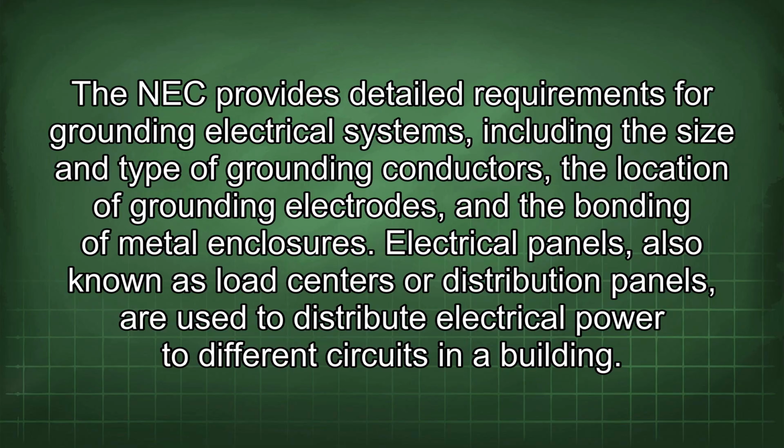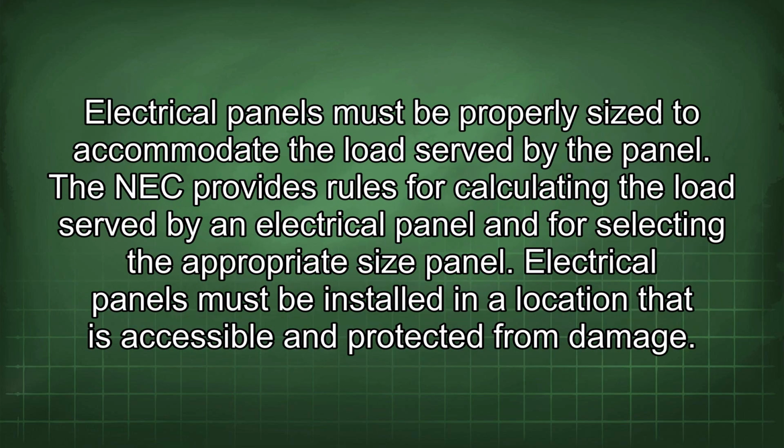Electrical panels, also known as load centers or distribution panels, are used to distribute electrical power to different circuits in a building. Electrical panels must be properly sized to accommodate the load served by the panel. The NEC provides rules for calculating the load served by an electrical panel and for selecting the appropriate size panel.